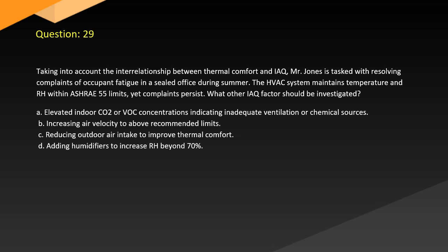A. Elevated indoor CO2 or VOC concentrations indicating inadequate ventilation or chemical sources. B. Increasing air velocity to above recommended limits. C. Reducing outdoor air intake to improve thermal comfort. D. Adding humidifiers to increase RH beyond 70%.